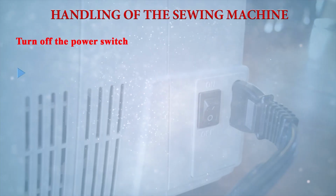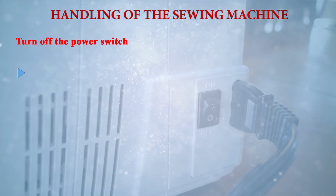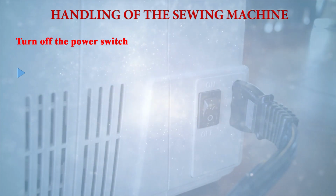So, don't pull the fabric at a time. Just stop the machine, then revolve the balance wheel and take the fabric out from that point. If you pull the fabric at a time, it may break the needle and it may harm you.